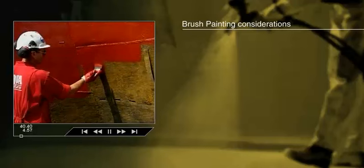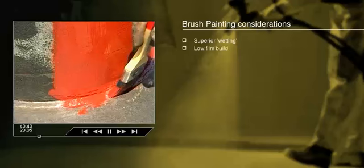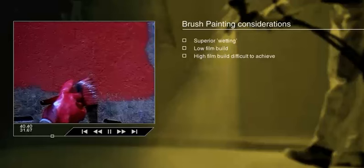For application of industrial protective coatings, there are three major points to be considered. These are: brush painting is said to achieve superior wetting; brush marks, that is, peaks and troughs, lead to areas of low film build. Consistently high film build is difficult to achieve, and lower film build should be specified.